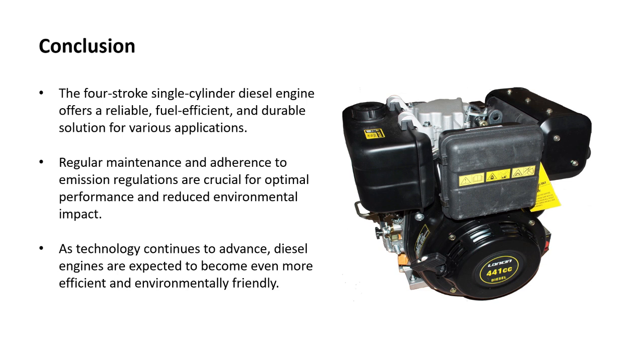Now we are at conclusion. That is, it's important to realize that four-stroke engines use a lot more components than two-stroke engines. Small two-stroke engines do not require valves. They do not require push rods. They do not require spring like those we have here, or rocker arm, or camshaft, or any of that.